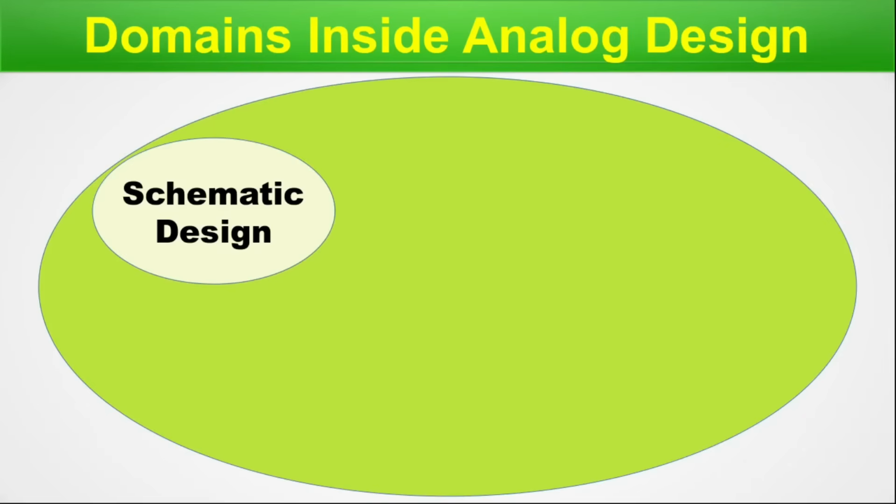Also, you can use small pre-designed blocks coming with your PDK design library. Once you make a schematic design, you can include all the SPICE analysis methods and run the simulation directly. Also, you have a choice to export the schematic into a spice.cir file and then simulate with your SPICE tool.